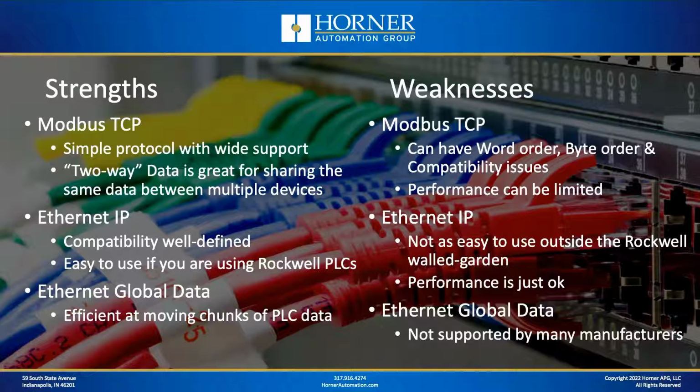Another thing I'll mention, and that is Modbus data is a register-based type data. It's a two-way type data. What does that mean? Well, for instance, with Ethernet global data and with the implicit or I/O messaging that's built into Ethernet IP, there's data that goes out to the network and there's data that comes from the network. So it's really separate variables are produced and separate variables are consumed. With Modbus TCP, the register data is basically two-way, so it can be read or written by multiple devices on the network talking to each other, which can be a real advantage.